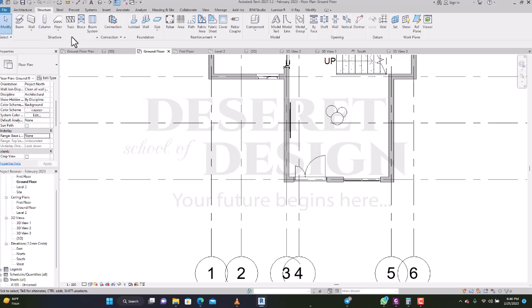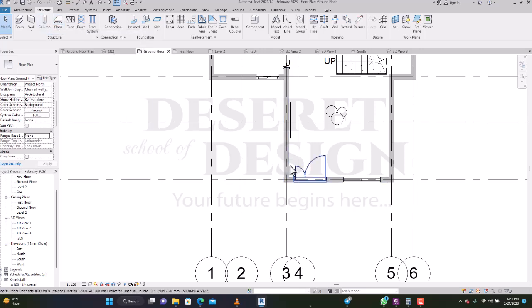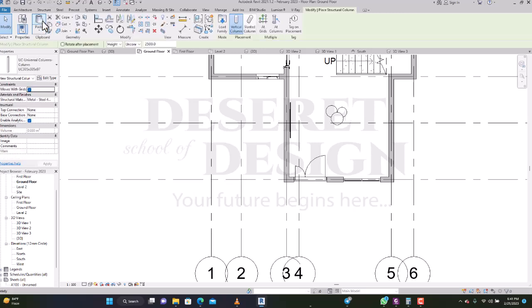There under the structure panel, we have the tools that we're using for the structural work. Now we have a beam, we have a wall, we have a column, we have a slab, a floor. Now if we are looking for a column, we'll click on column. Now this column, because we are dealing with what we call an architectural template, all those elements which are used in structure have not been loaded into this template. So what we need to do is load those things into this template. So we need to go and bring in a structure column into this project.